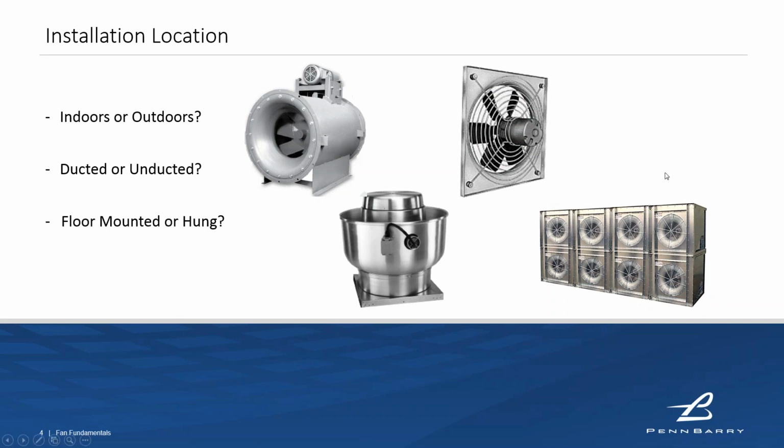These guys are kind of an outlier: fan arrays. They're pretty much exclusively used inside of air handlers. But they have a nice sweet spot in that you can design a system that has redundancy and a lot of ability to modulate performance based on load, because instead of having one fan, you have 2 or 4 or 8.